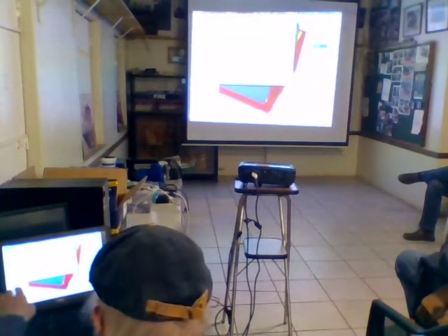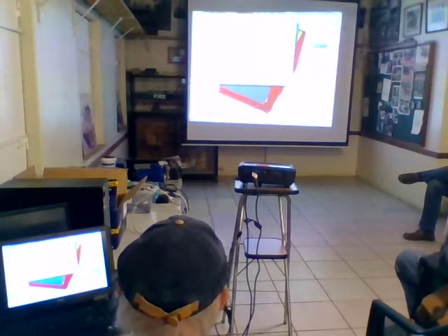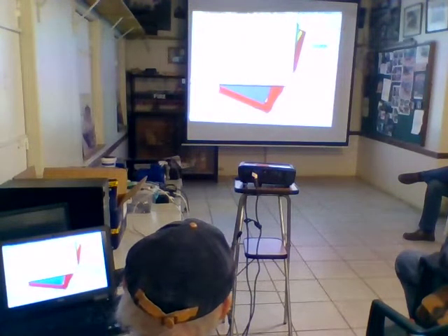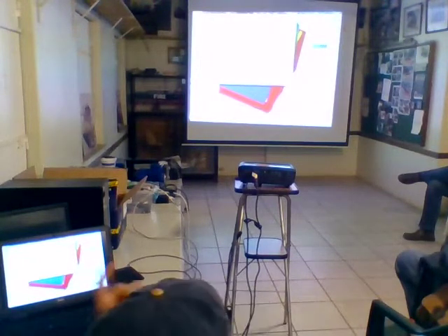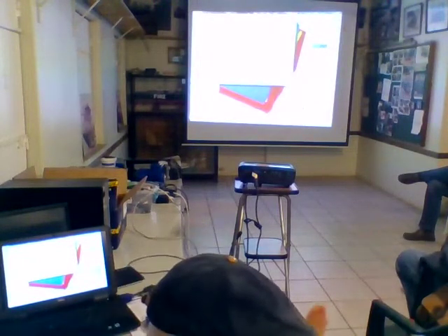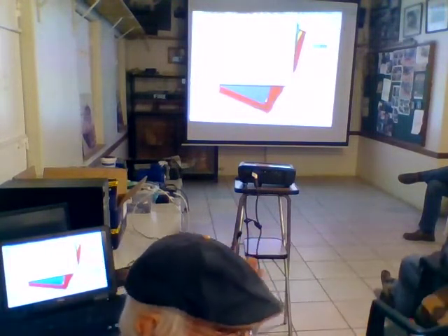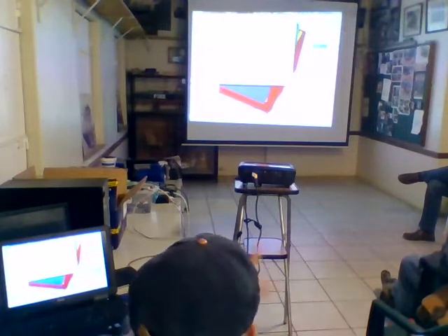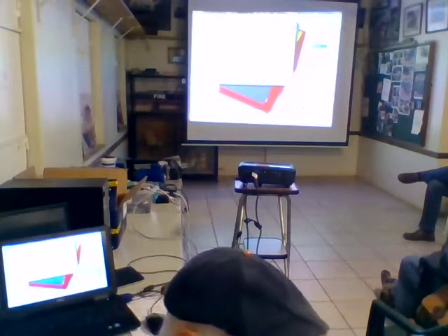See, there I've added these blue lines here, which are the deflections of the sides. By comparing various points on the structure, I can see where the weaknesses are. And this frame, even if it's open, is substantially stiff. We're getting less than a micron deflection on the sides.